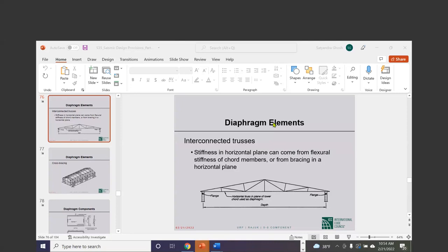I have no reason to believe it is incorrect. I mentioned again many times, even when you have shear walls and frames in the same building, near the very bottom of the building, almost the entire story shear goes to the shear walls and nothing or very little to the frames. This is why in a dual system we do the second analysis with the frames carrying 25% of the lateral forces. Otherwise, you will be designing very weak columns.